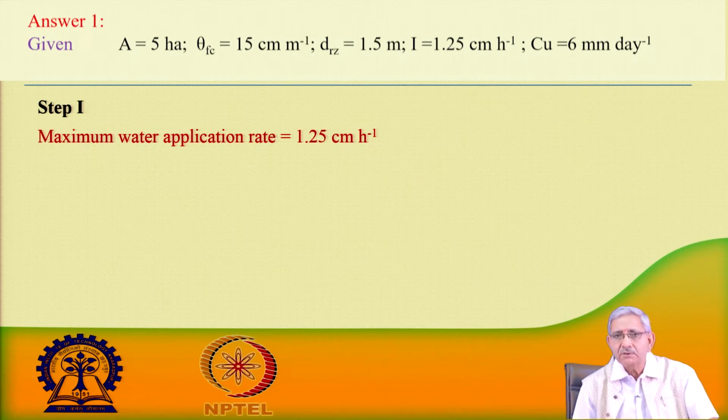The basic purpose of sprinkler irrigation system, as well as drip irrigation system, is that when we are applying water, it should not form runoff. So, it should always be less than the infiltration capacity, but the application rate should not be so low that the water does not fall and meet the requirement. It should not be such fine drops that they do not fall and remain in the air, which will be a huge loss of water in the form of evaporation.